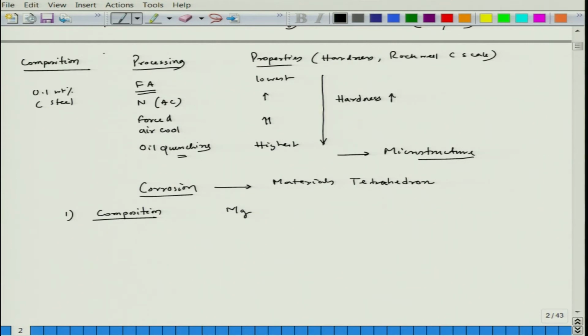Magnesium alloys have those specific uses because they have a high strength to weight ratio, because magnesium has a very low density. But at the same time, magnesium has a very high activity, meaning in terms of corrosion tendency, because it can corrode heavily, and that is what you must have heard about magnesium anodes.